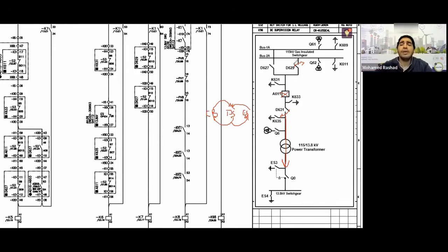Okay, great. How do I do that? He told you it's very simple. Now, if you close this disconnector, initially you need to check a set of grounds, right? What are they? This ground, and this ground. You might say they are already open, but I'll tell you, sorry, it's the law. We set a law, and unfortunately, with its advantages and disadvantages, you will have to check them anyway. Okay, great. You check them? Oh, okay, fine. You are reassured that they are open. Well, inevitably, you have to make sure of that electrically.